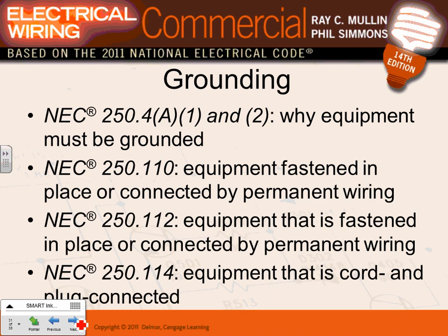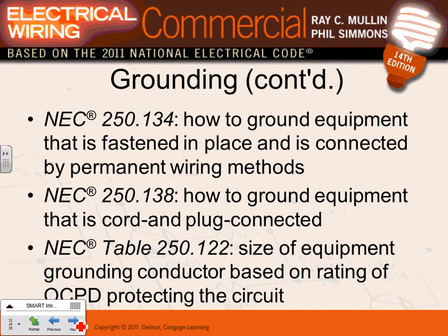Grounding. Every single piece of equipment must be grounded, period, done. So you have to pull an equipment grounding conductor with every equipment. And these are all the articles that tell you, if you have a plug, if you have a cord like this, and you plug your machine from the cord, the grounding conductor is going to be inside the cord, right? And taking your ground from the plug.